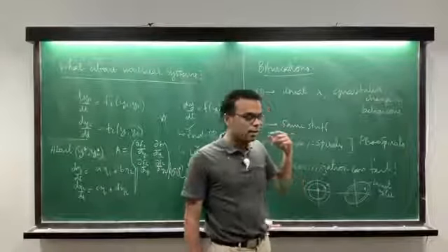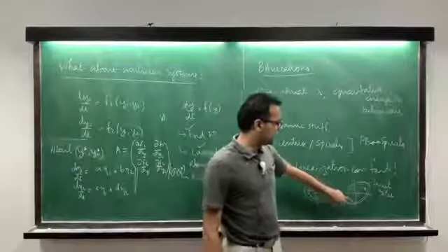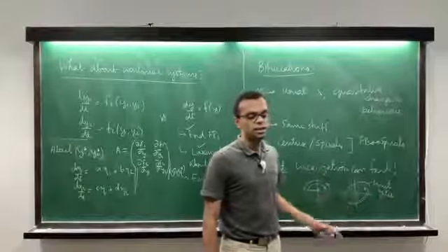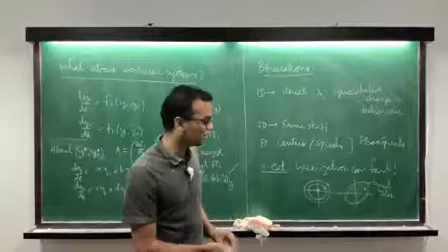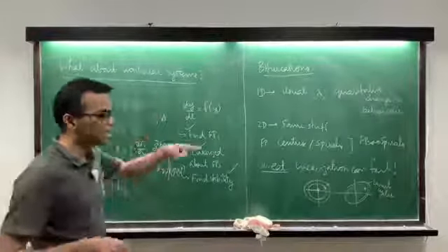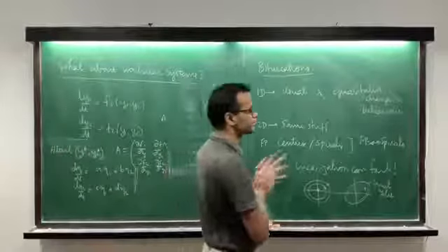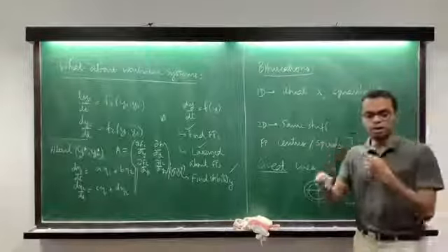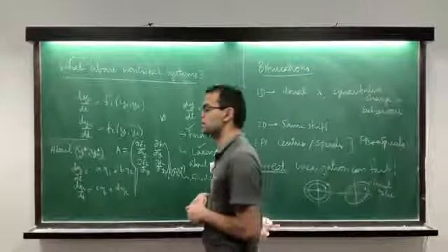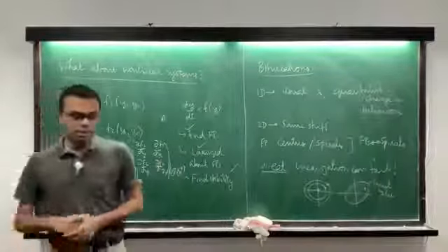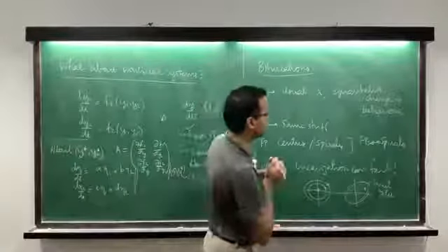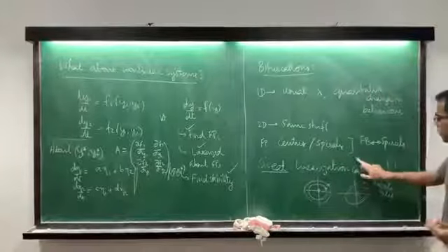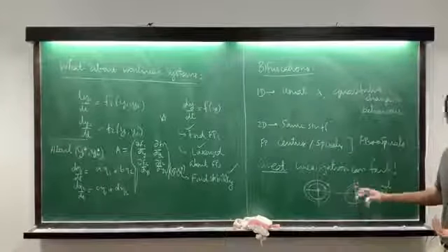There is a way to work on systems like this. You can convert to polar coordinates and look at trajectories deviating from a potential limit cycle trajectory. There are perturbation techniques that you can use to detect limit cycles, to look for periodic solutions of the ODE and use that to identify the presence of limit cycles. There are geometric methods. There's something called the Poincaré-Bendixson theorem that tells you how you can identify limit cycles by looking at what trajectories far away are doing and what trajectories close to the origin are doing.